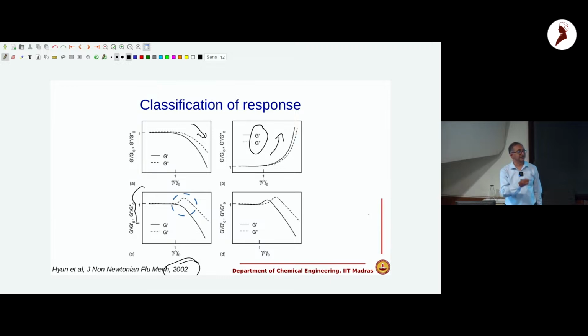So many of the soft matter systems that we are familiar with, we will see that G prime decreases, but G double prime goes through a maximum, and quite often, like in the egg box bundles that I showed, our interpretation was that those egg box bundles come apart at some strains, and therefore a lot more dissipation happens, and therefore G double prime goes through a maximum. So depending on the material system, a lot of our hypotheses are related to some increased dissipation in those strain amplitudes.